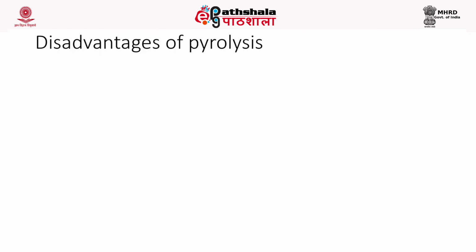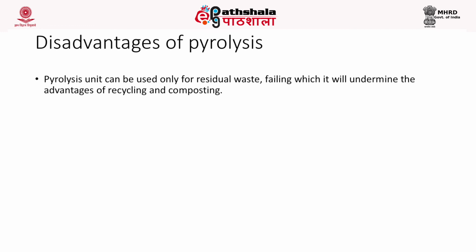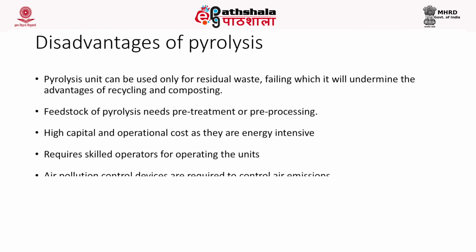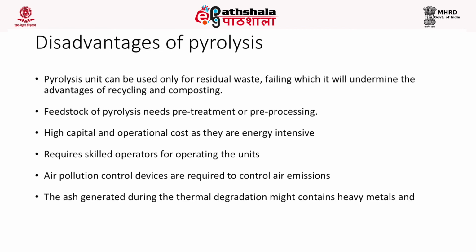Now, coming to the disadvantages of pyrolysis. Pyrolysis can be used only for residual waste which cannot be recycled or composted. The feedstock of pyrolysis always needs a pre-treatment or pre-processing. Again, the process is energy intensive and it needs a high capital and operation cost. It requires skilled operators and some air pollution control devices should be installed. The ash that is generated during this thermal degradation will contain very high levels of heavy metals and hence will need safe disposal.